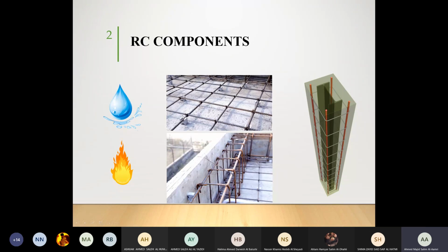These are the cover blocks that you are designing and you are taking into account while you are doing the design. Now, when it comes to steel and fire, there are different methods. One, as Khalid said, by painting it, or the other method which is more effective, which is called encased. Encased in the sense that this is your steel column, you are covering it up by concrete. So whenever you are covering it up, we call it encased.